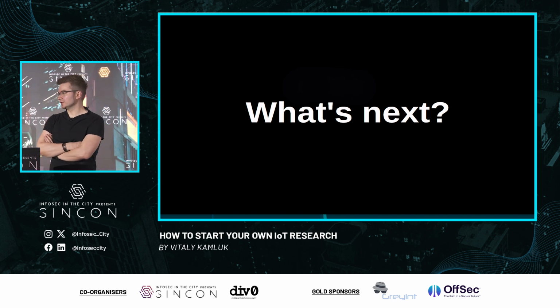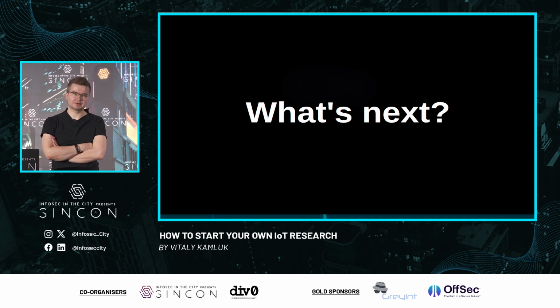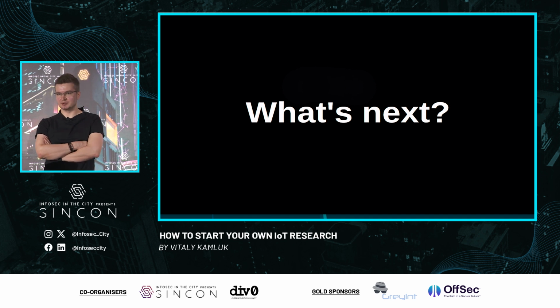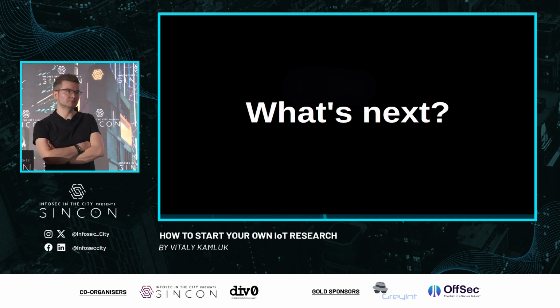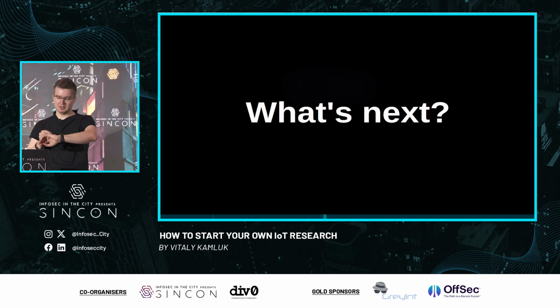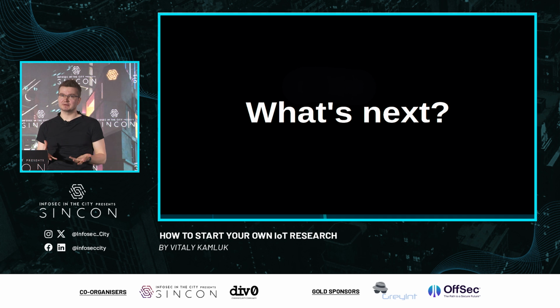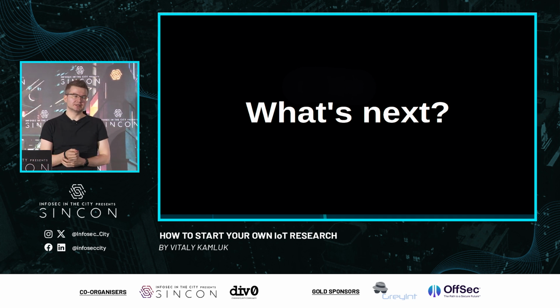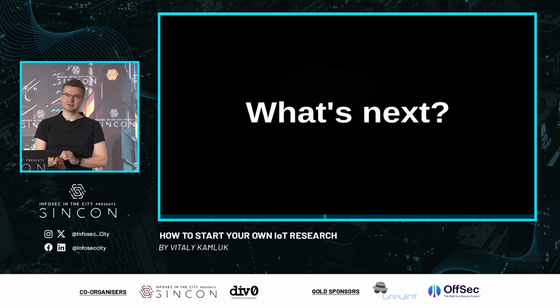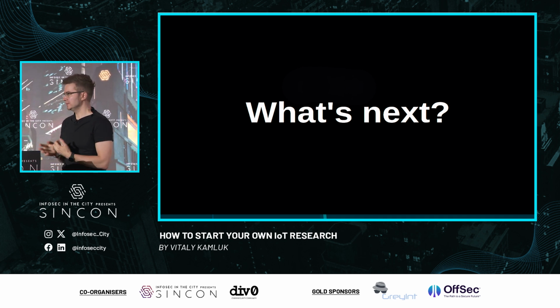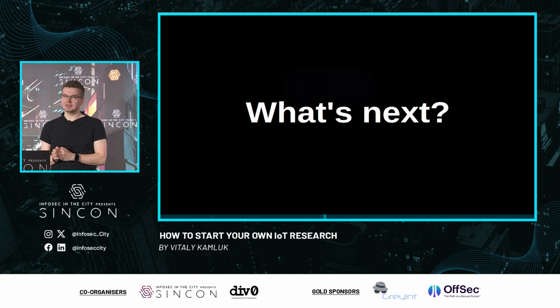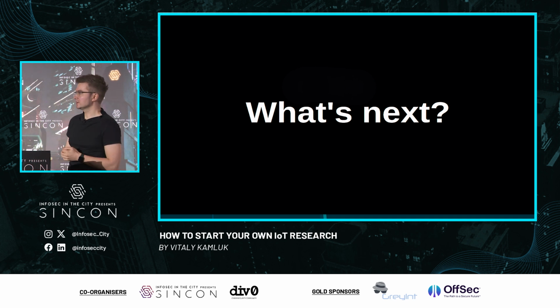The idea to get root and to get a shell on the device is as follows. There is normally a bootloader that is used on most of these consumer devices. One of the most popular open source ones is called U-Boot, and that one can be used. It's kind of a pre-system shell that allows you to interact and change settings of the booted system. And what the device has on the firmware is a mini embedded Linux. So if you can change the boot options of the kernel of that Linux instance, you can pretty much do single user mode.